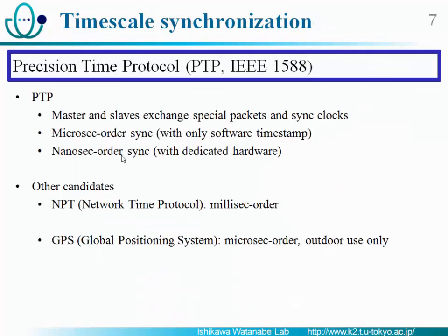In this scheme, we use Precision Time Protocol, PTP. It is standardized as IEEE 1588. This protocol provides very accurate timing clock synchronization with only microsecond order synchronization error.